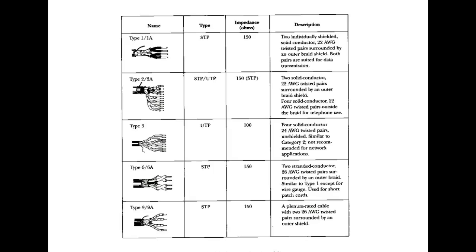Impedance, have we talked to you about that? We did talk a little bit about XL and XC, right? So when we start adding capacitors and inductors to circuits, we pick up what we refer to as impedance. Impedance cannot be measured with an ohm meter. Y'all understand that? Because it is an AC characteristic. So if I was to take a UTP conductor and put an ohm meter across it, it's going to measure infinity if they're not connected together.